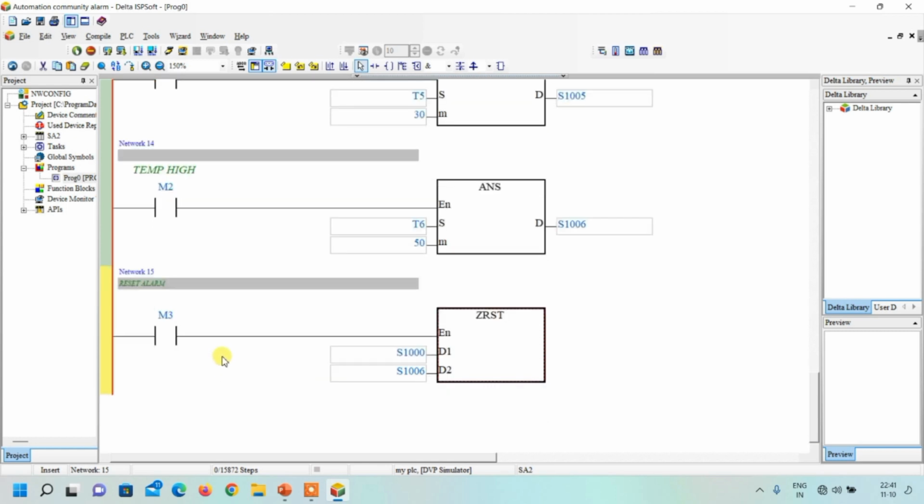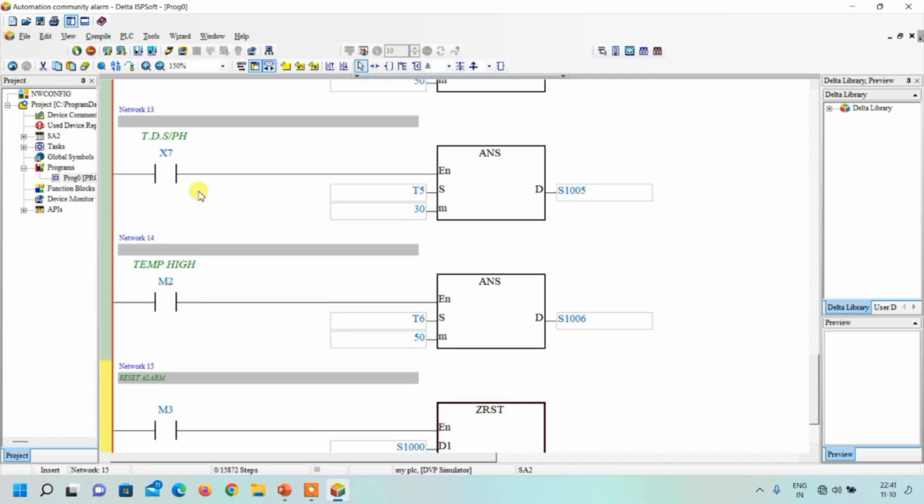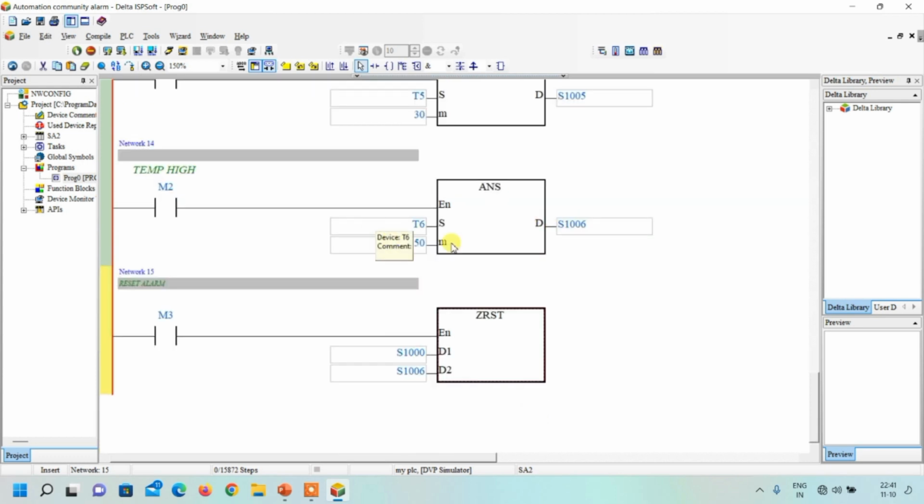Now you will say, if I press the reset button, but even if the fault is there, what will happen? Once I press this button, alarm will be resetted. But if fault is still present, it will again execute the particular code and set the particular alarm. Until the fault is cleared, alarm will keep coming. So this is all about the complete programming of tower light and alarm message for HMI. It's HMI designing and simulation we will see in the next part of this topic.